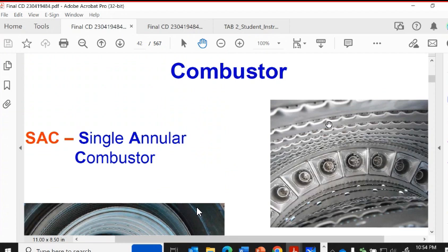And so what that means is you've got this crisscrossing, air inside going out and air on the outside coming in, and it crisscrosses back and forth all the way up and down the combustor shell through here. And so that keeps an even temperature on the combustor liner itself.